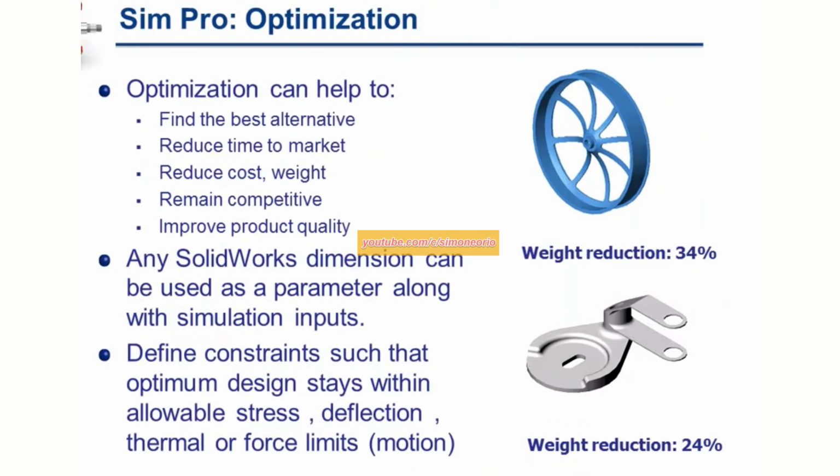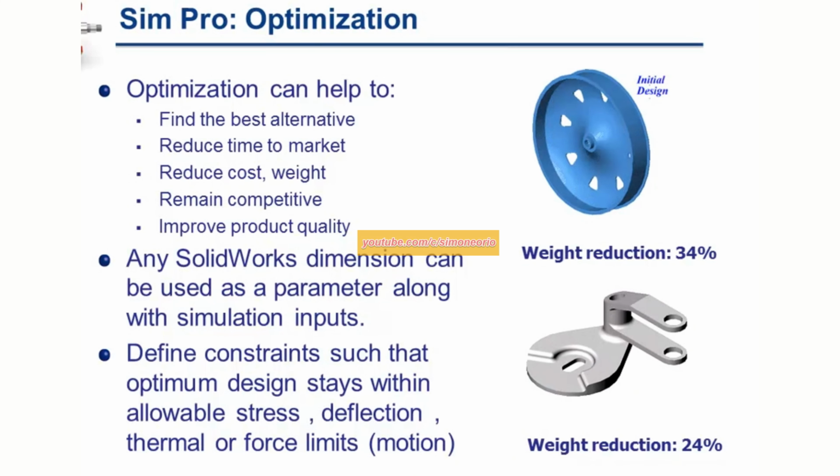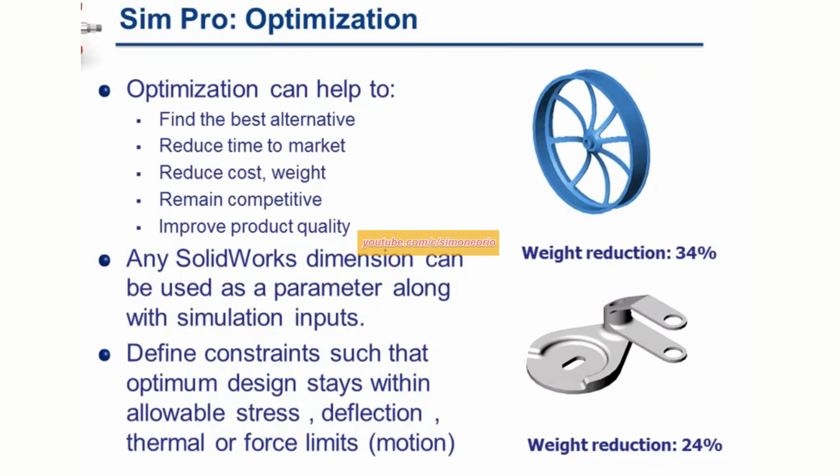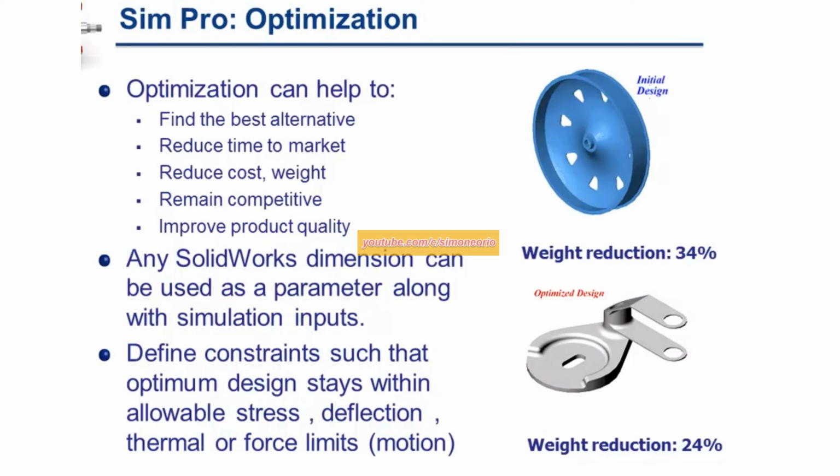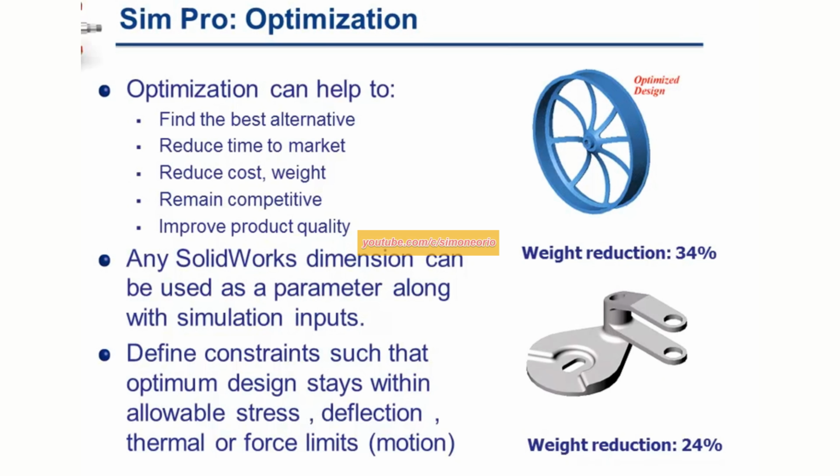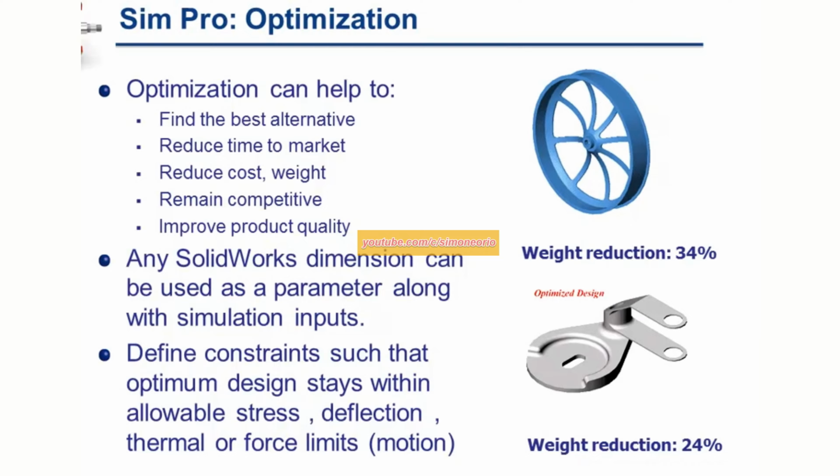And I'm going to combine this using our optimization tool. In optimization, we can have sensors in the model that track displacements, stresses, strains, and forces through connectors. Then we can change feature or sketch parameters and use our optimization solver to determine which direction the design should go to meet stress, deflection, or frequency targets. We can run multiple analyses at once, frequency and thermal at the same time as a stress analysis.